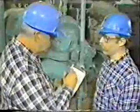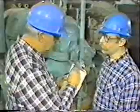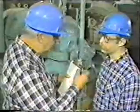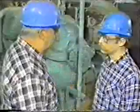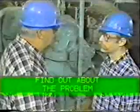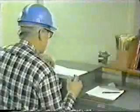In the last segment, we watched the troubleshooter question the operator, perform an operational check, and check the manufacturer's instructions. He's been looking for as much information as possible about the problem and about normal operation. Another source of information is plant records. You can find information that might give you a clue about the cause of the problem by looking at the operating logs and the maintenance logs.